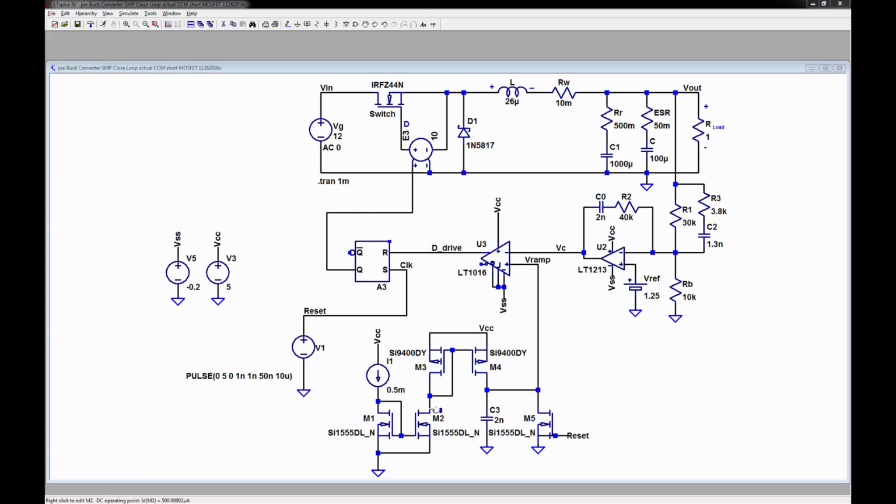Now, we don't want a current sink. We don't want to pull down. We want a capacitor. The current has to flow into the capacitor. So we can't put a cap here. It's not going into the capacitor. So we have to build another mirror. This is an NMOS.